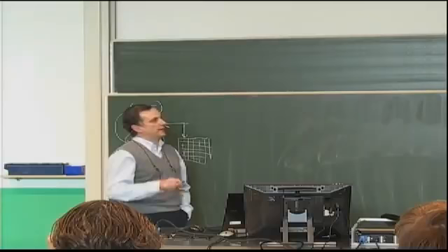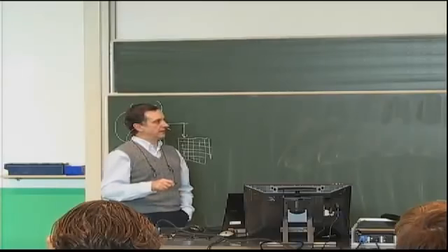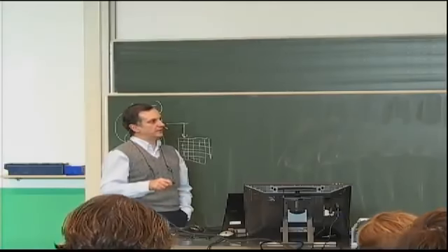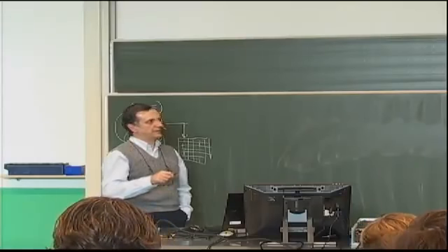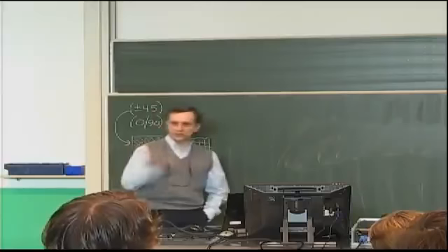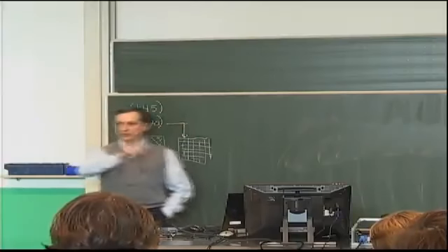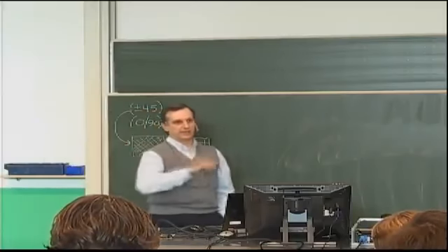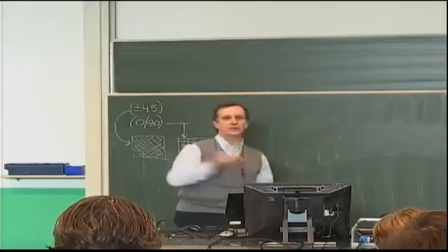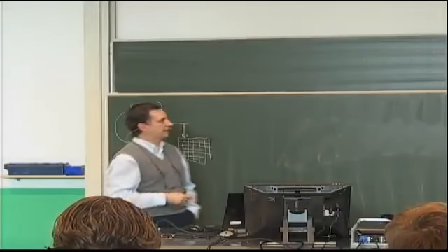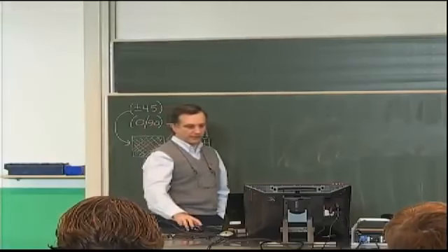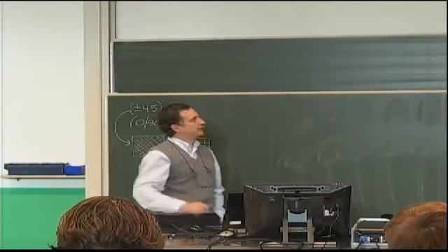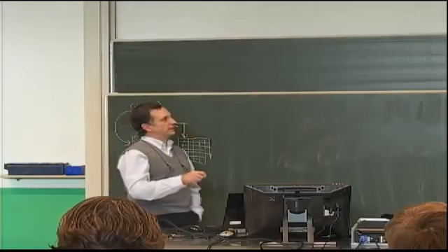The Fourier series will have this form, and the BMN are unknown coefficients. And we use sines on purpose here because we have sines in the W expression, so that when we substitute in the governing equation, we'll be able to match terms of the same coefficients of the same term, sine times sine. To determine the BMN, we go back to Fourier series theory, which says take your infinite series, which